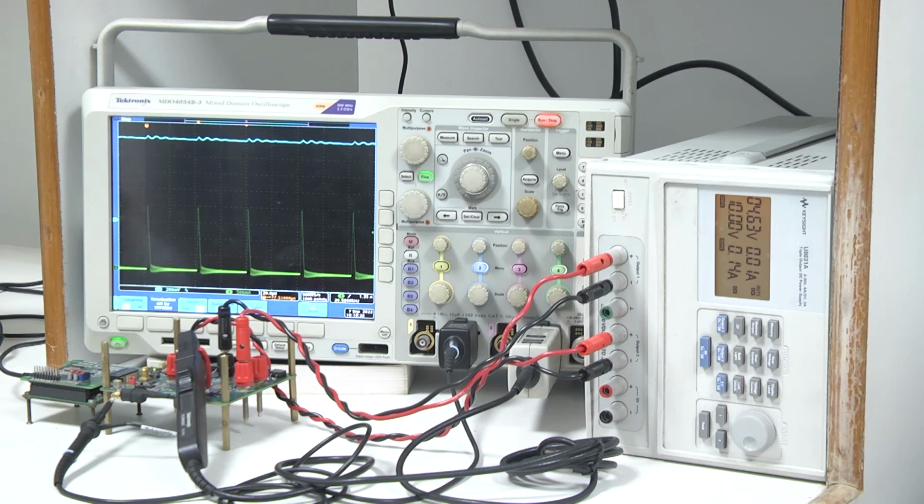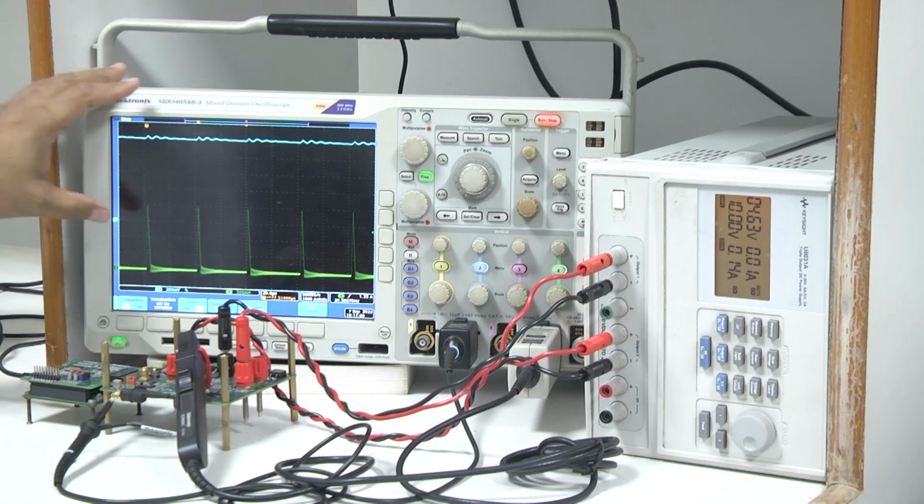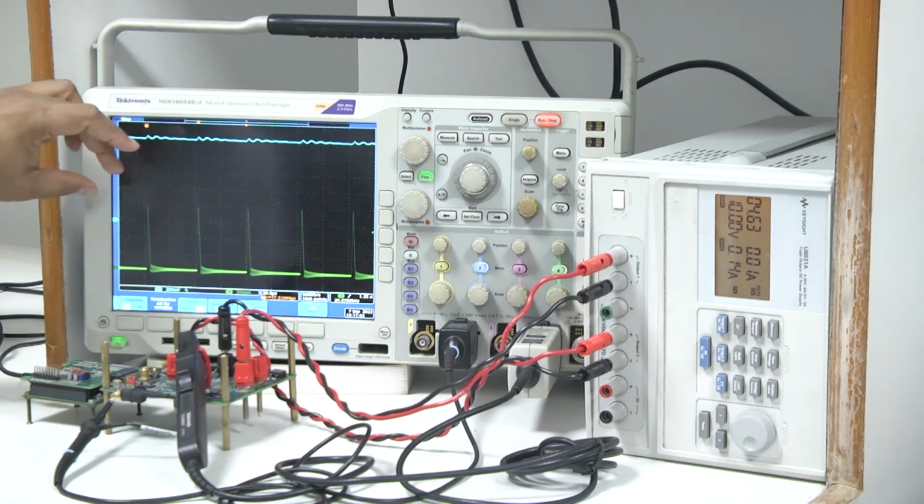As a result, the slope of the current is increasing, and the current ripple is increasing. So it may increase the voltage ripple also. That is one of the problems in constant on time if you use a timer based on time. I will demonstrate in another lecture adaptive on time, where this can be taken care of. But in this lecture I am going to show that you are getting a pulse frequency operation under light load condition.